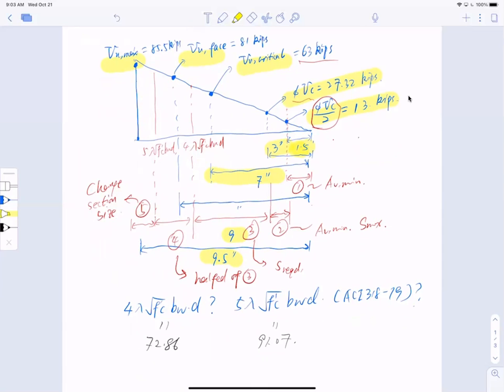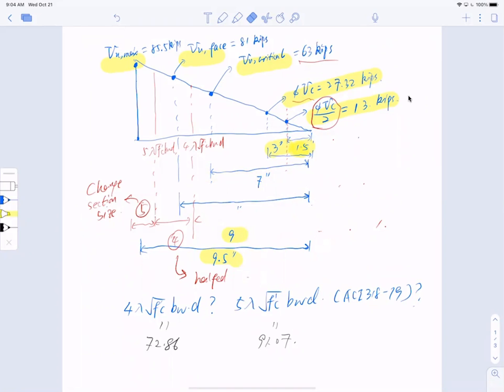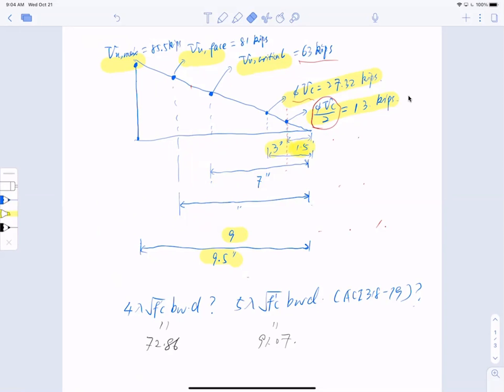Before we start, I mentioned that we're going to design it for different zones, etc. Let's just remove that for now. Don't want to complicate things yet. So let's take a look at the constraints first. What are the limitations? We have talked about there's going to be a maximum shear resistance taken by the cross section, and there's also a maximum shear resistance that the web reinforcement can take.